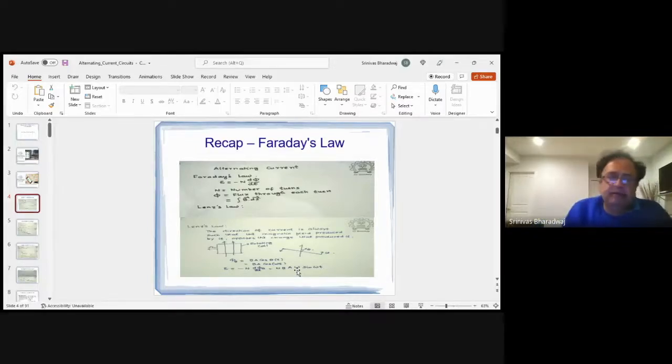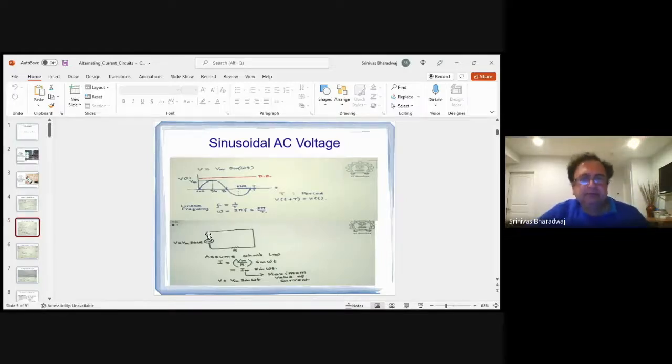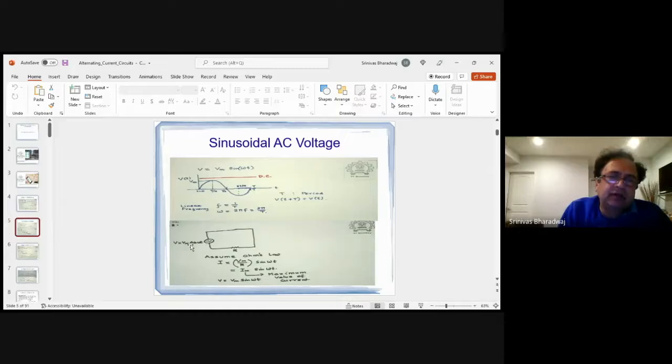Okay. So that is the voltage, right? That drives the power the circuit can generate. So if you have V times I, it will produce corresponding power. Now you have a sinusoidal voltage. If you had just a resistor, the current through the resistor will be in sync with the voltage. So if this is V sine omega t, the current will be Vm by R sine omega t.